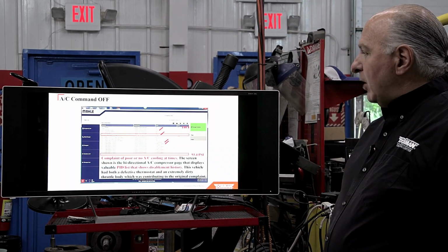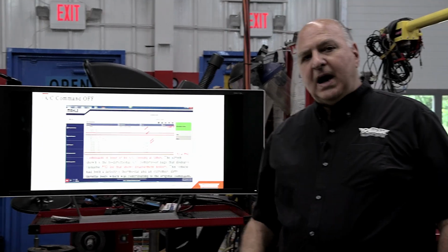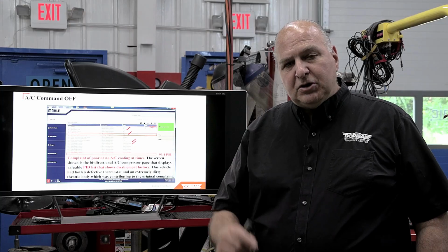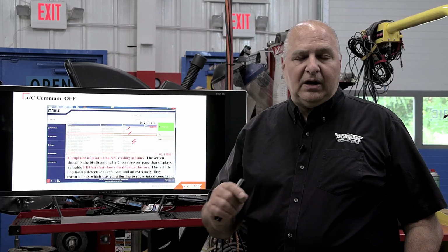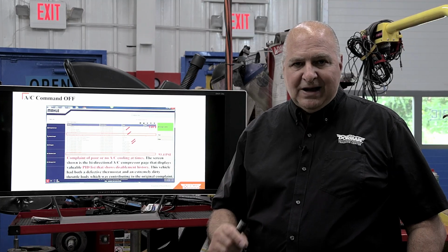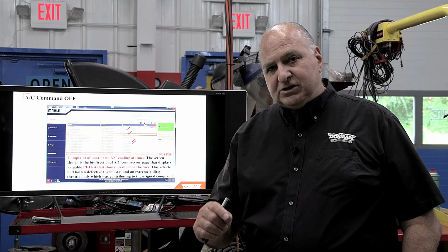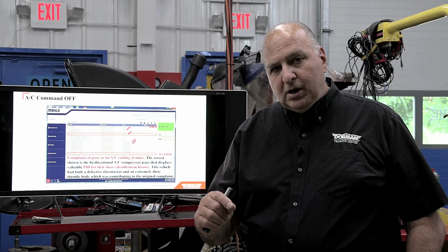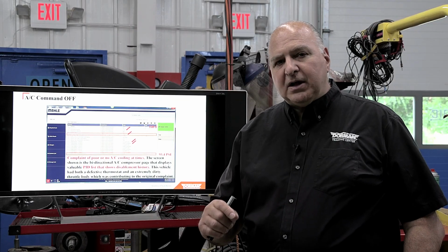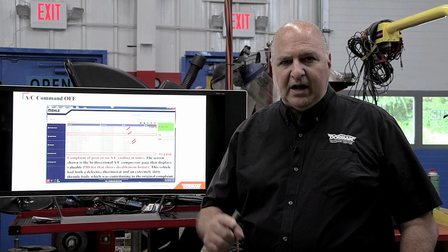So here, let's talk about coolant first. Well, coolant is super important, right? And what type of coolant we put in, where do we find that information? RTFI, read the freaking info, right? Because there's so many different antifreezes and coolants. And what water we put in, it could be tap water, GM says. It could be distilled water. And it could be deionized water. Deionized, make a note, especially deionized if it's an electrified compressor.